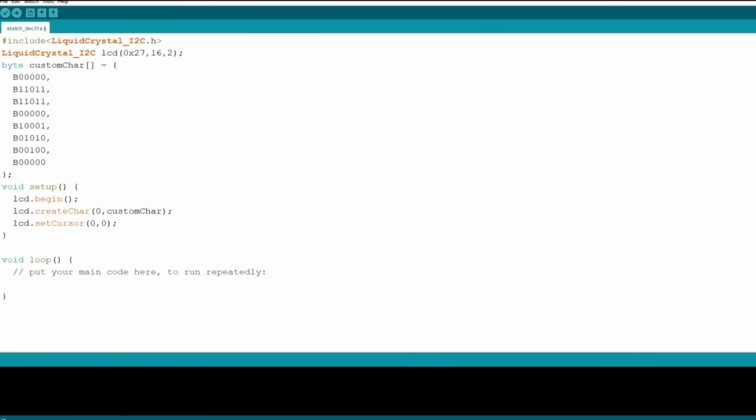And then let's move to a new line and we will learn a new function here too. Our function name is the write function. With this function, we can show the data in our ID number on our LCD screen. So let's write here lcd.write, open and close parentheses, and also put a semicolon, and let's move inside of our parentheses. We will define one parameter here. The parameter will be the ID number. As you remember, our ID number is 0, so I will write here 0. If we do something like this, we get the result we want.